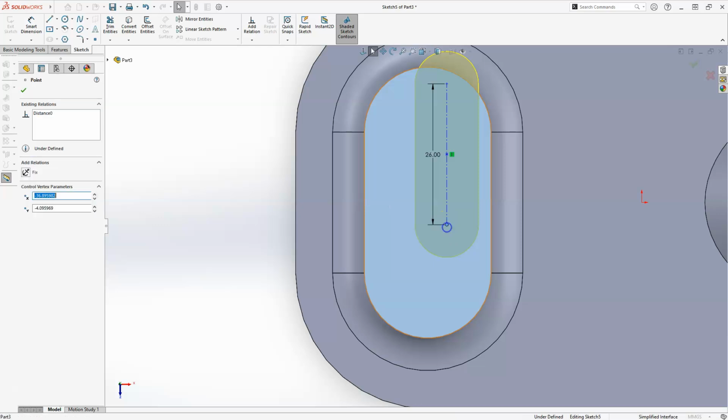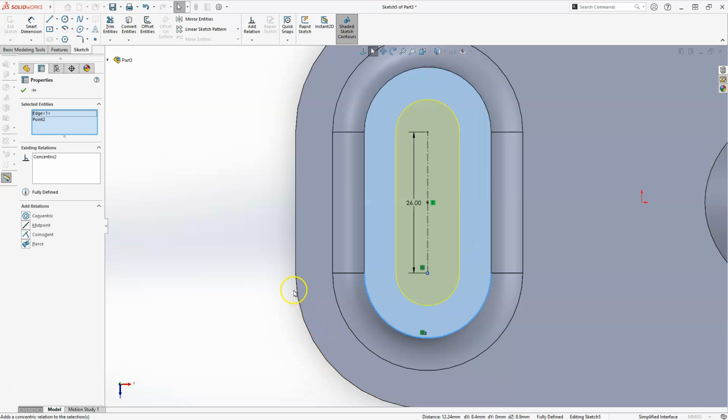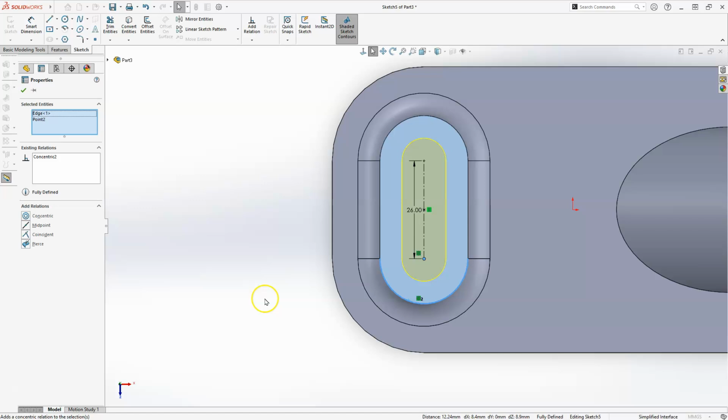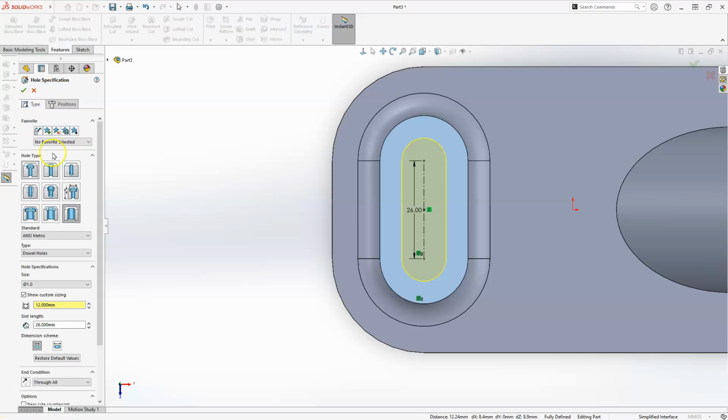Okay, so I'll select here. Let's go ahead and hold down the shift button, and then select and make it coincident to this one. So we have about everything we need. Let's go ahead and put a dimension on here. Oh, I keep forgetting I'm inside of the actual hole command, and I have to come over here to type. And that's what gives me my diameter.